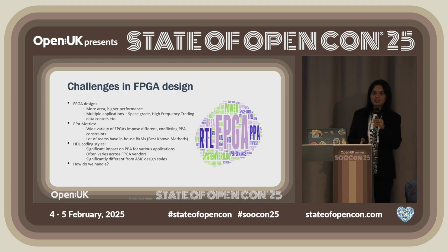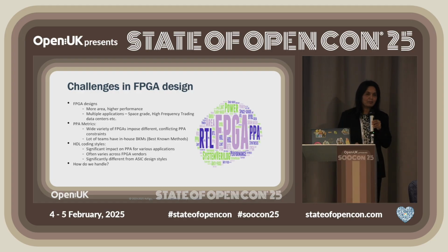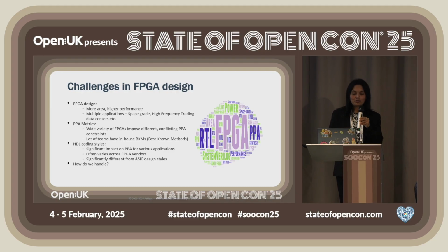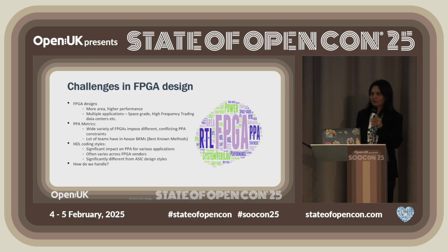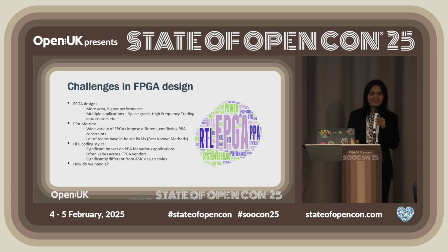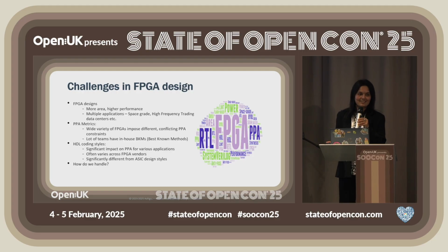All right. That is how the top-level landscape looks in terms of FPGA. So what are the challenges in your FPGA design? The moment we mention FPGA, it is PPA: power, performance, and area. Am I using my resources well? My performance is met, but is it really handling the load, or is it burning? Is the area effectively used? And is the power low?